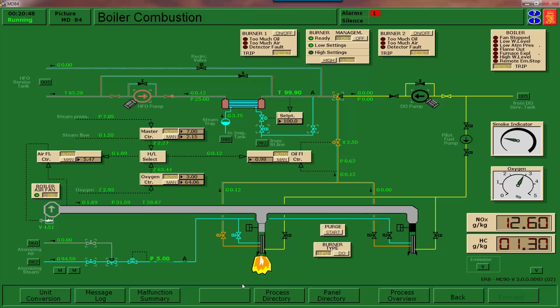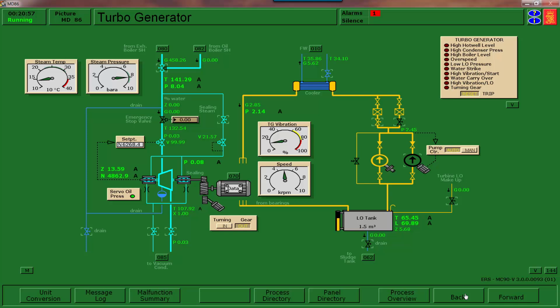boiler combustion. And I like to drop this down to 6 bar. Once this boiler is cycled off, this helps prevent it coming back on unnecessarily. And I'm waiting for the steam temperature to come up. And you can see it's coming up now.